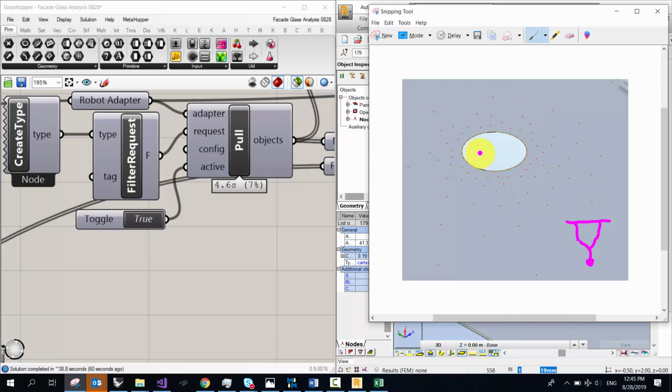So what we said is, what's the way that we can get that behavior, but computationally? What would be great is if we had a node here that was actually pinned, analytically constrained to be a pin, and then off of that we had a bunch of constraints, rigid links, right? Would everybody agree that would probably get us the right type of behavior, right? That's a question. Yes. That's what we want. Do we want it to be a pinned connection basically at that point at the middle of the spider?